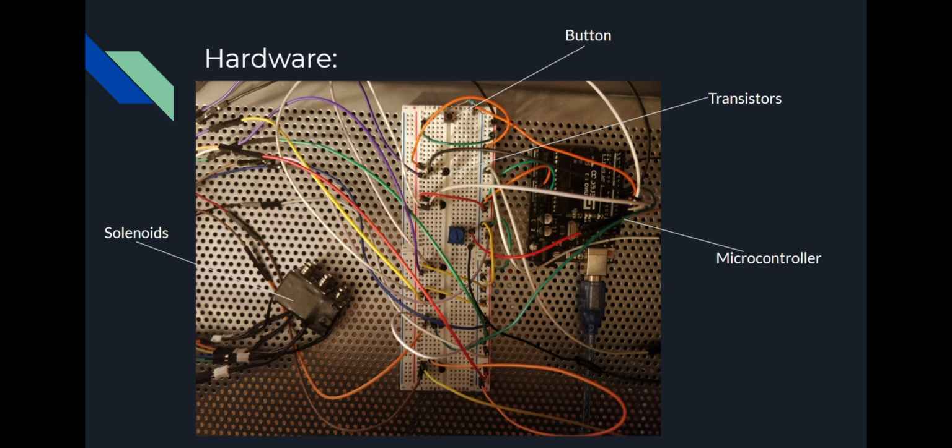Next, for the hardware, we have 4 main components. The first being the microcontroller. Here's where we do our main logic, our solenoid logic, and where we receive the information from our Bluetooth module. The Arduino will receive from the Bluetooth module and output on its digital pins. A problem we faced with the digital pins was that the maximum output of an Arduino digital pin is too low to power any solenoids.